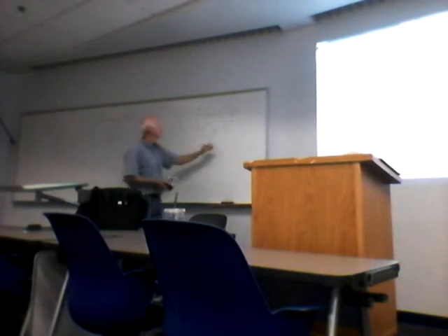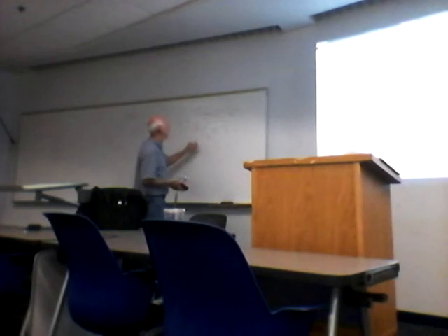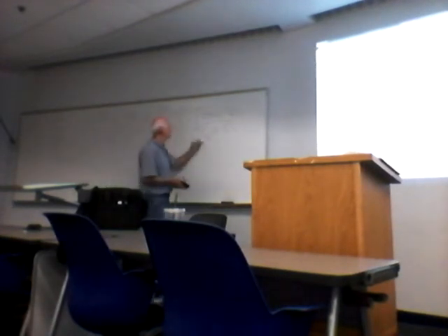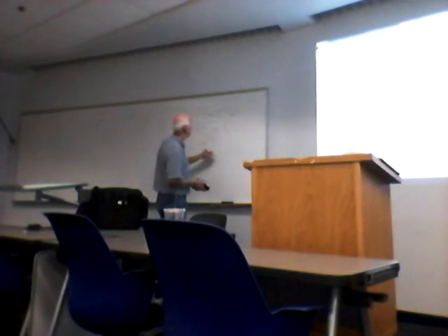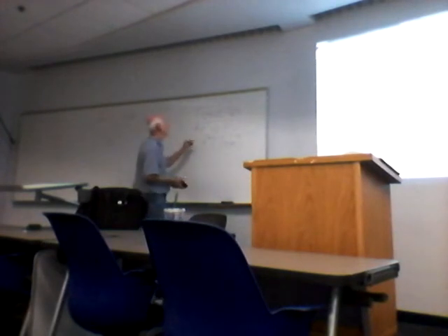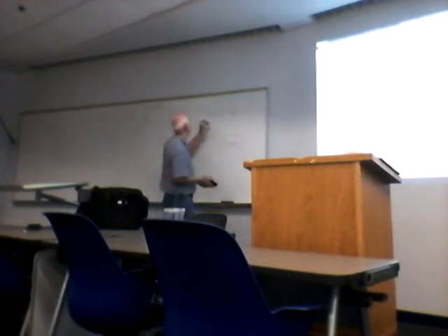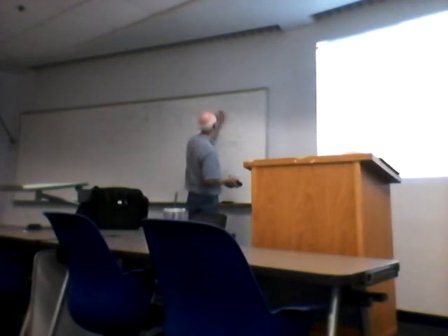So that goes in here. Sigma at sea level is 1. And the coefficient of lift would be given. I'm not even going to make you look it up on a chart, so I say the coefficient of lift is 0.4, whatever. I'm not pulling the number out of thin air. So I put in 0.4 there, times 1, so that doesn't change, times 500. That's the bottom part of the equation. 295 times, let's say, a heavy airplane, 15,000 pounds, whatever it's worth. So that becomes 15,000 here.